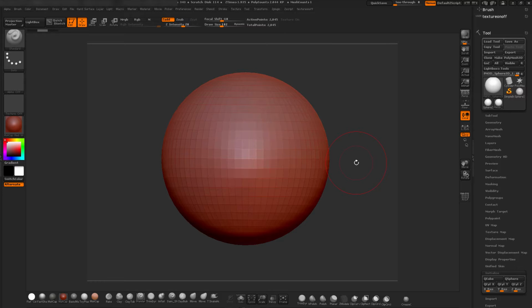Now how do we get the detail into the mesh? Well, we subdivide it. If you look at these squares, every time I do a subdivision, each of these squares or quads will become 4. So it multiplies by a factor of 4. Very quickly we can put resolution into the mesh, but also the file size or the polygon count will multiply by a factor of 4.